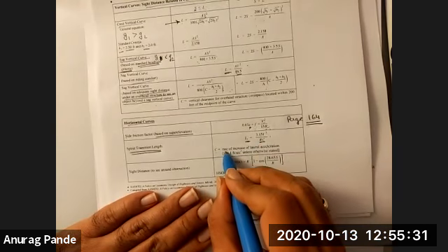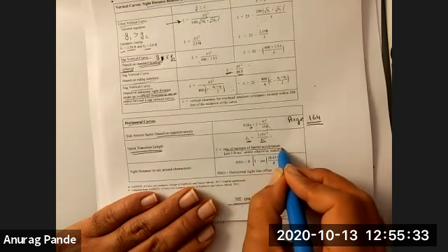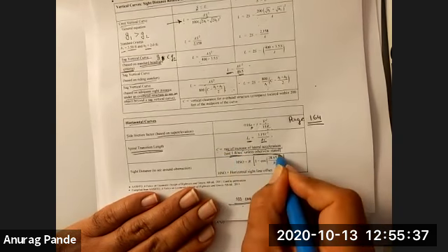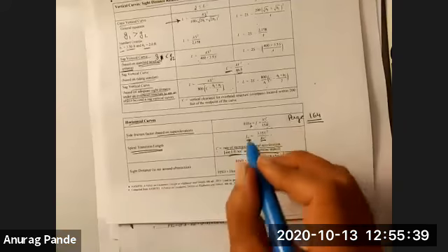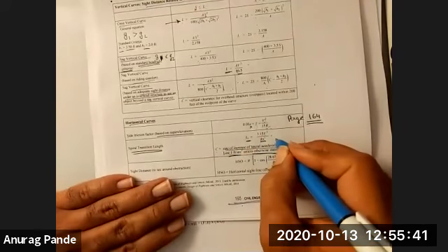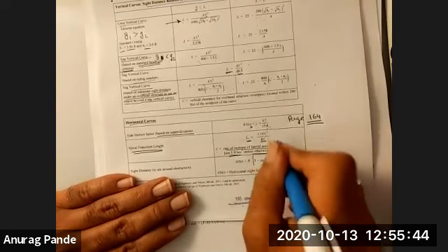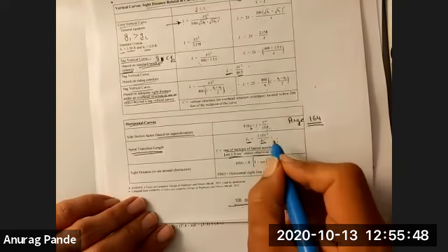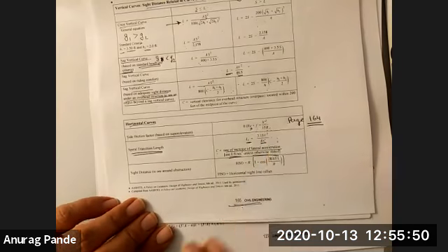C is something that is given here, the rate of increase of lateral acceleration. Use 1 feet per second cubed unless otherwise stated. So this will be a given value. If they ask you for a problem on spiral curve, this will be a very plug-and-chug kind, and you will be able to figure that out. I do not expect you to be able to design the full spiral curve for the FE exam.